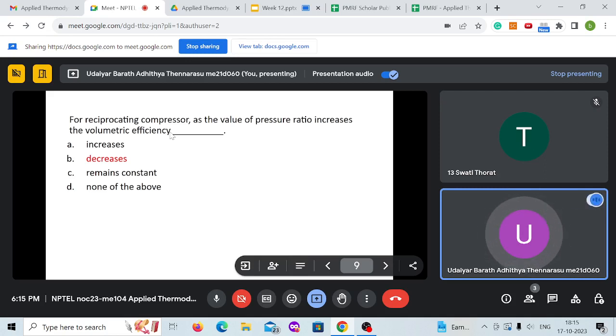If you take a practical reciprocating or piston type compressor, it is working at some pressure ratio. You have some clearance volume that is required because you have valves and also a seat. So based on the construction features, you require some clearance volume to be there. When you compress the air or any fluid inside, the pressure reaches the higher discharge pressure which you want, so your valve opens, and the fluid which is there goes out.